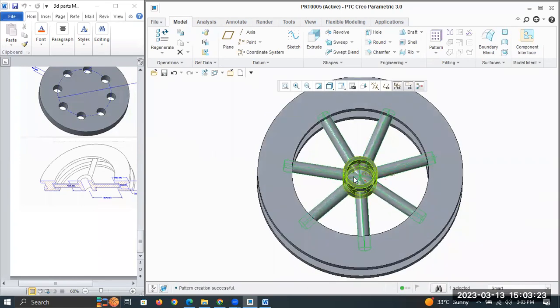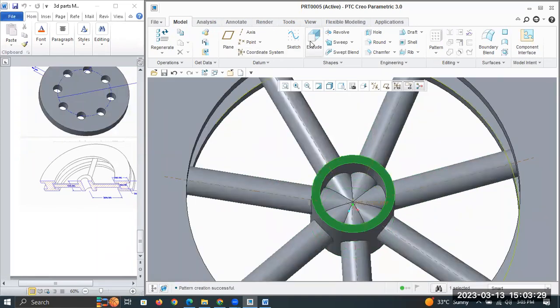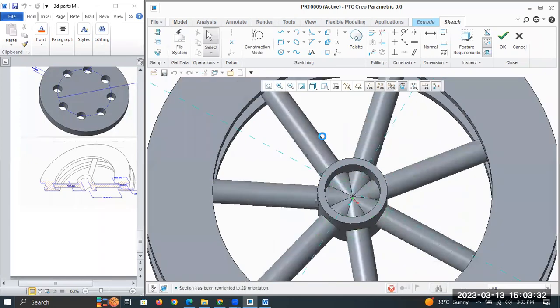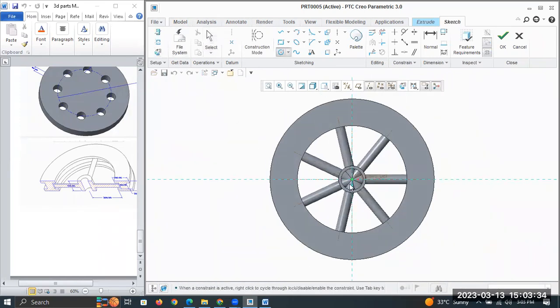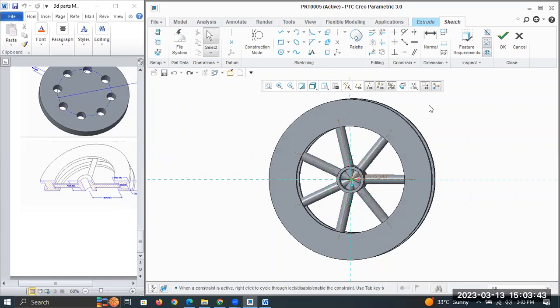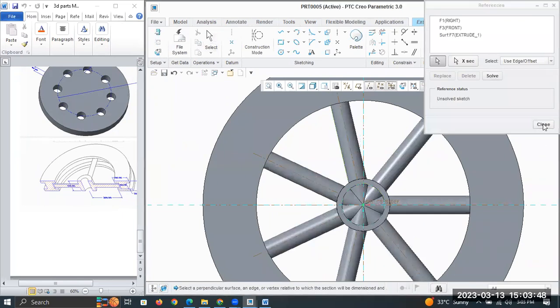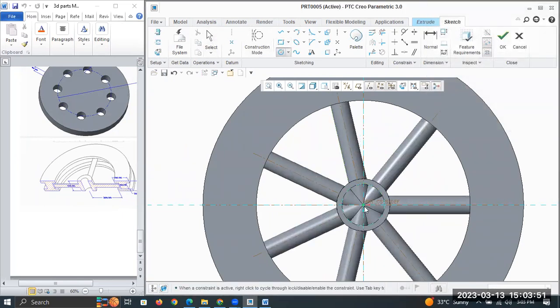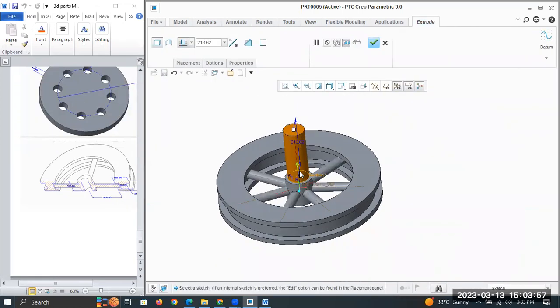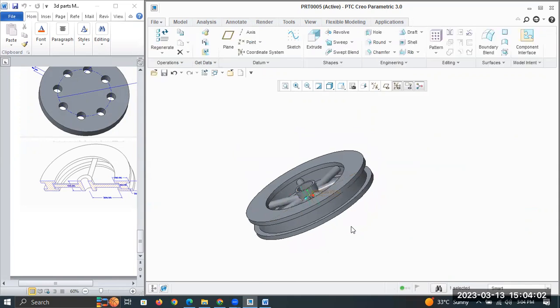Of course, as we have taken the center as the reference, now I am going to select this particular face, top face, extrude, sketch view. Let us drop the circle here. Okay. So yes, you are right. Dimension, if you forget, then you will be in trouble. Only thing you please take this as a reference. Select a circle, drop the circle this way. Now say okay. Alter the direction, cut the material. Right? Say okay. Is that clear?